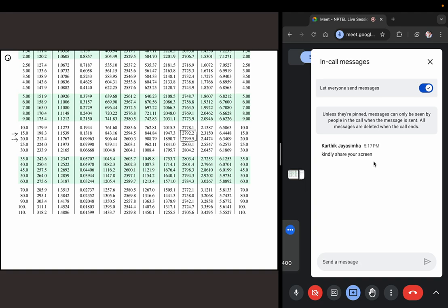In our case, this is at 15 and 20 and we need it at 19 bar. So 19 bar will be somewhere between these two values. And the value of enthalpy that we got from the isenthalpic process is 6.3. So this value is actually less than the value that you will obtain at 19 bar. So at 19 bar, if you do the linear combinations, you will get a value of